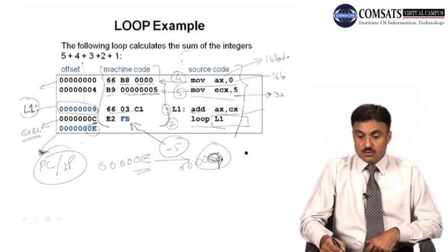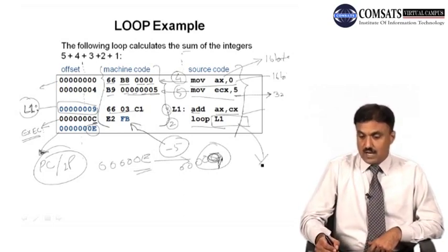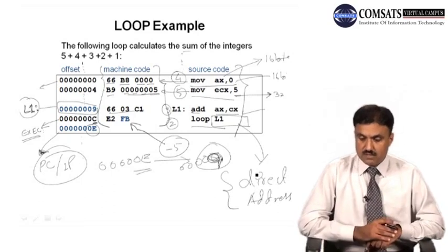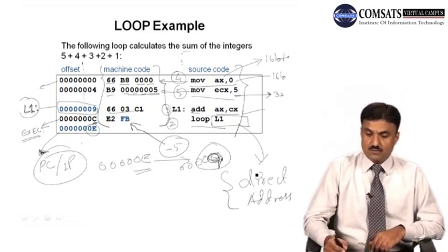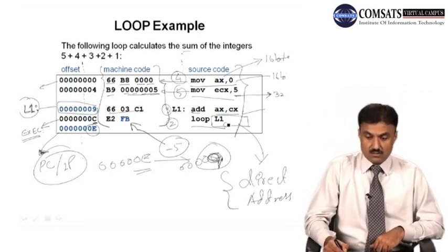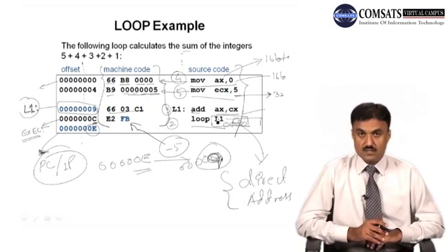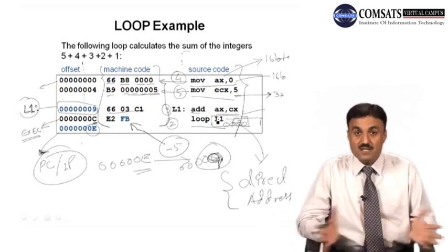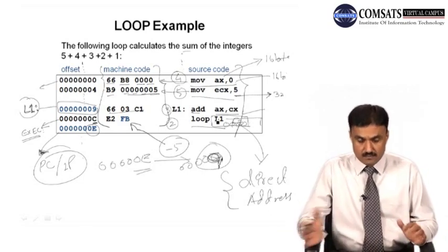In some cases, when we use flat memory, it has a direct address, because there are no segments, only direct addresses. So it will have the direct address like 0000 something, or F7, 1, 2, 3, 4, whether the address size is 20 bits or 32 bits. So it has the complete address in that case.